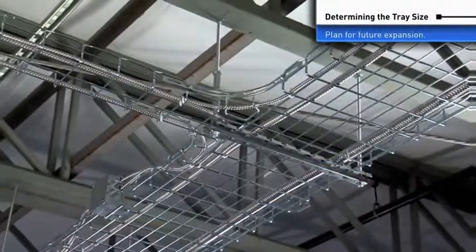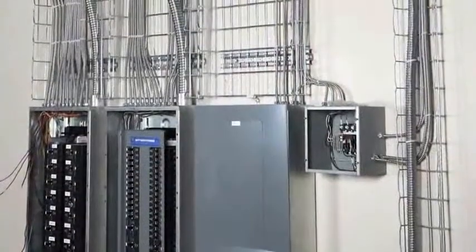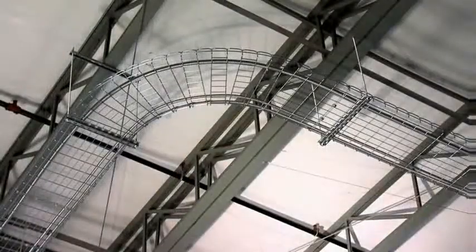Think about the future of the installation. How much growth should be planned into the system for future use or new technologies? At a minimum, the spare or blank breaker locations and spare equipment slots should be used to determine additional capacity.